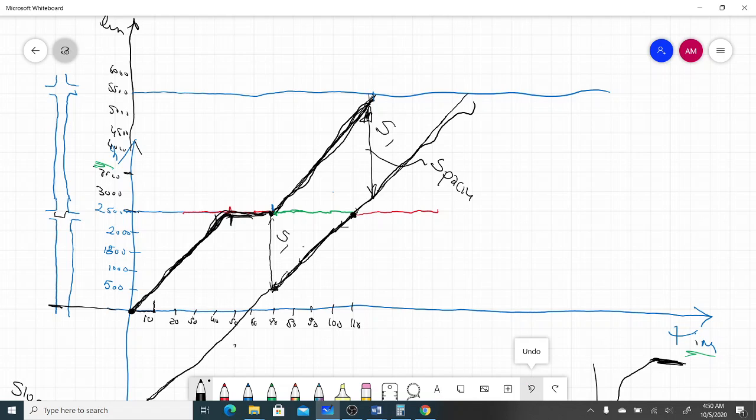The spacing is the distance between the first and the last car. And this spacing should be the same based on the speed. And this spacing should also be the same for the first one here. So we will adjust the speed. So you're going to draw here two lines with the first speed, the first slope like this, and then the second speed, something like that. If you're able to draw these two lines, the first line of the first car and the second line for the last car, you can now calculate everything you can on the curve.